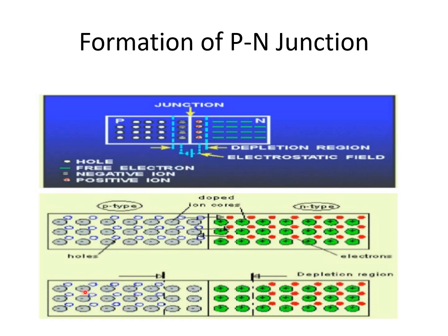At the same time, the holes in the p type are unable to cross, there is not that much force. That means it is open circuited, we just combined p type and n type, we did not apply any external force. These electrons and holes are unable to cross the depletion layer to constitute the current.